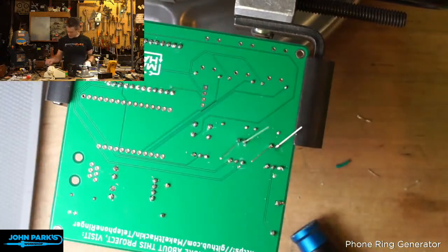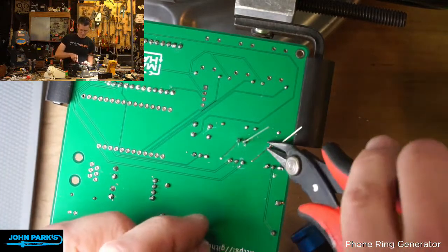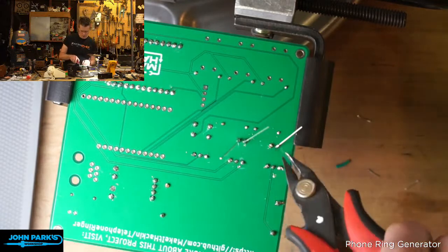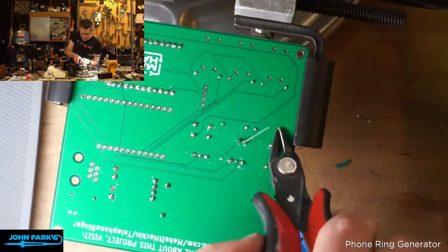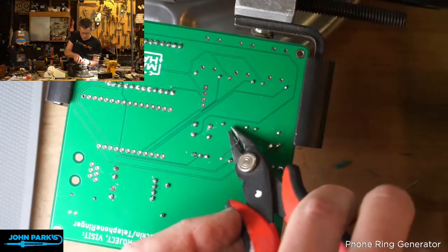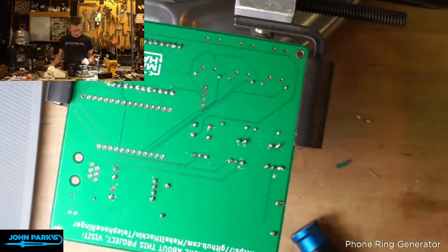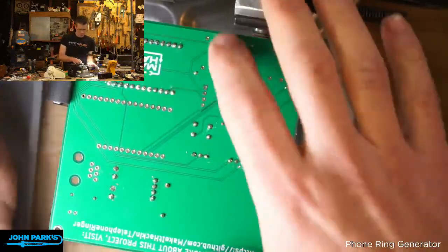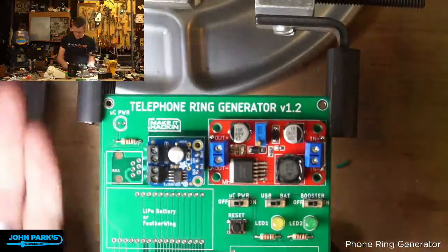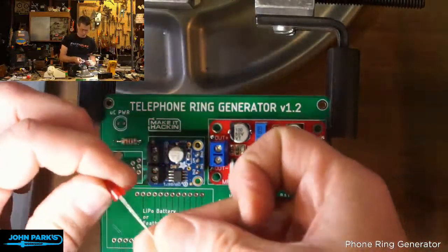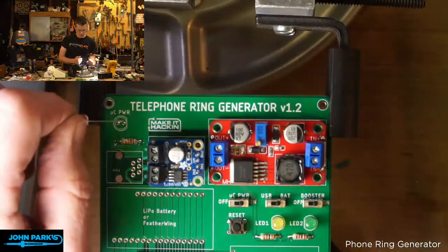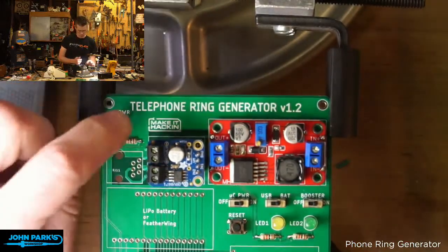So let's gnaw these off again. Oh my gosh, I swear there's a spot on here where it actually contacts the other side fully. There it is. There's like one good spot on these cutters at this point, because I filed them poorly. All right, so let's do the other LED, why not? So again, short leg, flat side, and this one faces a different direction than the other one, so you just got to pay attention.